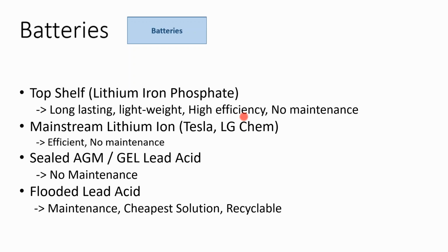But even if you're saving 50% over 30 years, just coming up with the capital for that purchase becomes a project disqualifier. So, when you see the high-end lithium iron phosphate batteries that cost $1,000 a kilowatt hour, those might not be the best for running a home off grid.